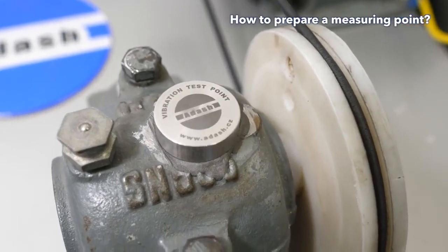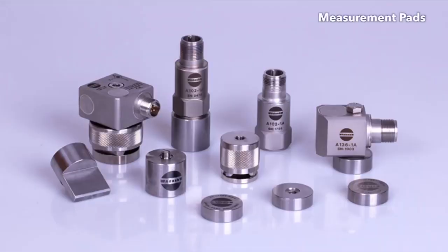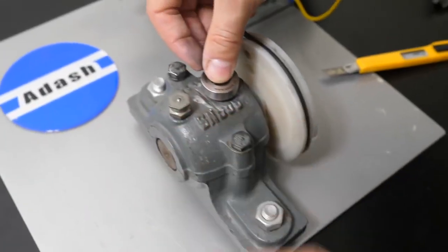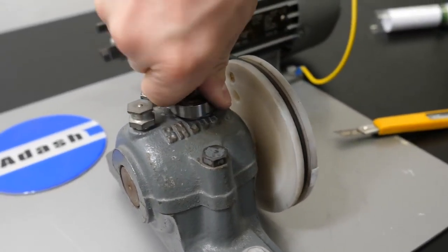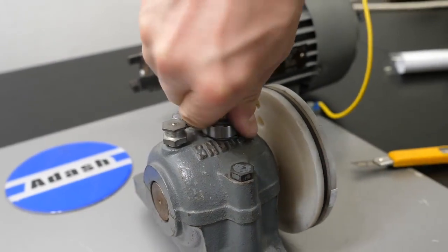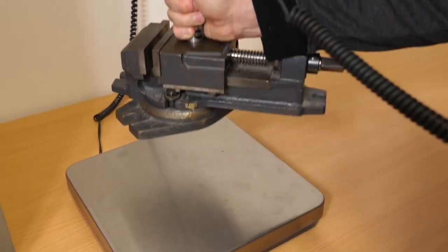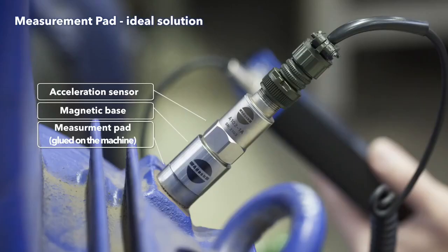To obtain quality and repeatable measurements, you should prepare your measuring point on the bearing housing. The best way to do this is to fit all measurement points with measurement pads. A measurement pad has a flat ground surface made of magnetic stainless steel, and it is connected to the machine with a special glue which has metallic properties when dry. This ensures good vibration transmission. An acceleration sensor is usually supplied with a strong neodymium magnetic base, which ensures good transfer of machine vibrations to the sensor. So, the ideal measurement point solution is glued measurement pad, magnetic base, acceleration sensor.